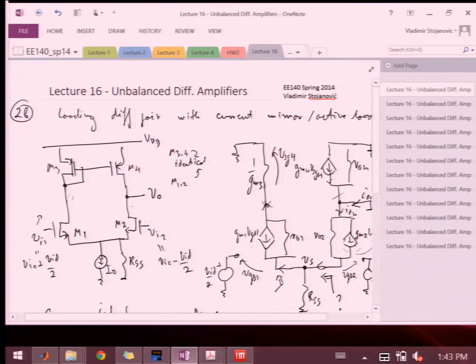It's going down, right? Because all this is like one resistor, right? And you're pulling more current from it. So this node has to go down. Okay, so this node is going down. That node is also directly driving this gate. So if that node is going down, where is this going? Up.